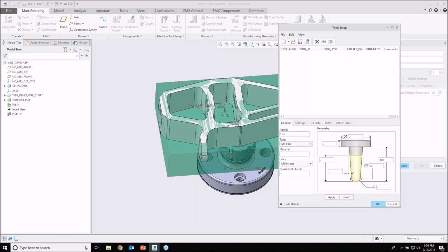I'm just going to create an end mill, and it's going to be a 16 millimeter end mill. Let me quickly go through that as well. So here are all the tools that you can create. The nice thing when you do it on the fly is it will choose this automatically. So if I'm busy with the drilling sequence and I don't have a drill, and I go into the tools, then I can only create the drill because I'm busy with the drilling sequence. I'll show you that when we go to the 4-axis bit.